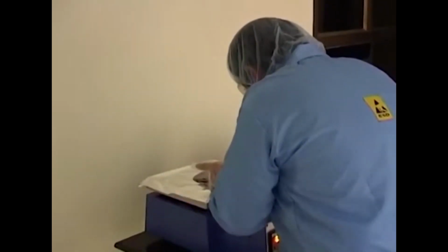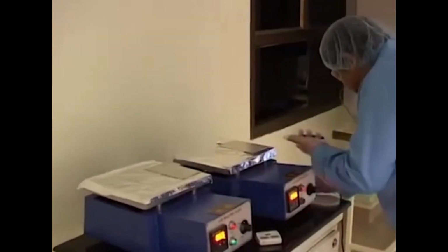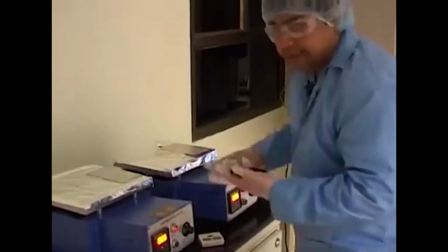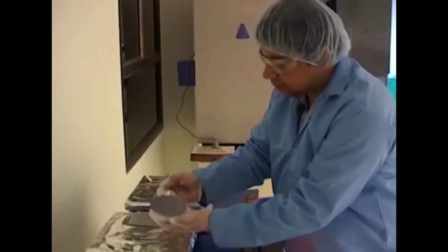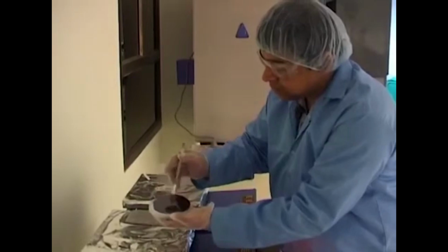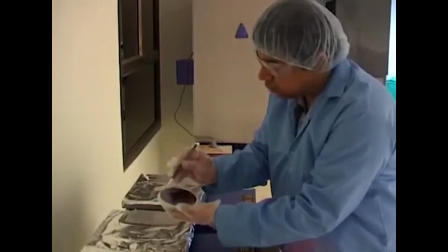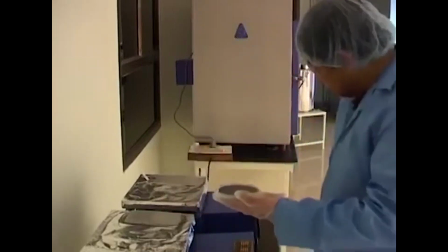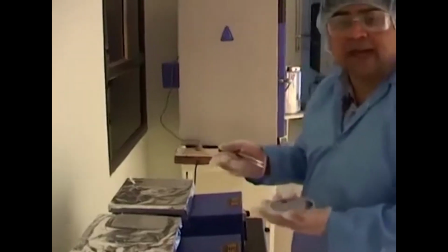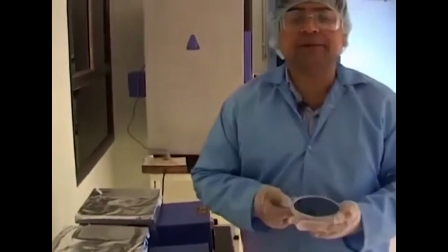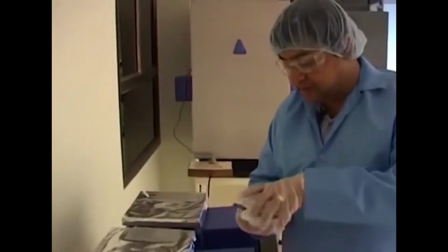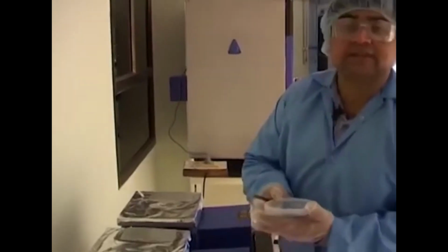You need to hold the resist from a very small corner here, and then slowly put it over the surface that we want to put it. So I am going to now transfer this resist coated wafer onto this particular surface. It is always a good idea to hold the heated wafer at room temperature and let it come back to the ambient room temperature, so that the film has the least possible undulations and warping. We will just cover it in case there is any dust accumulation on the surface.